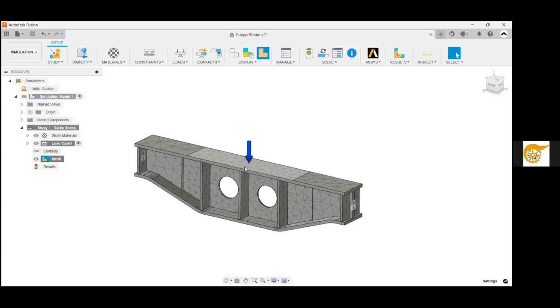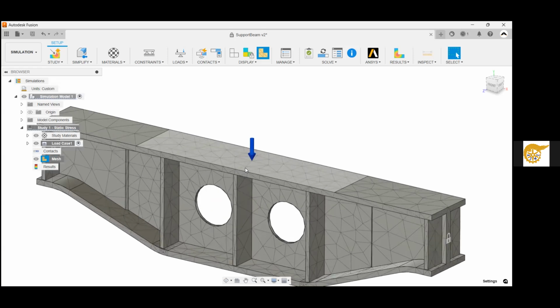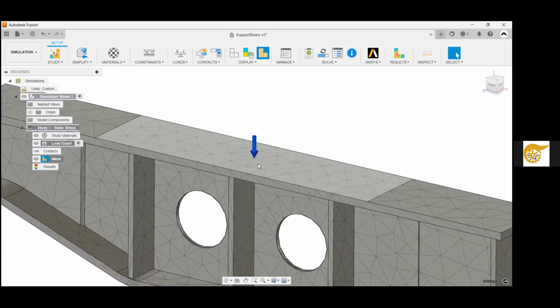You want a fine mesh in areas that are small, especially. So, for instance, on the top face here, if we have, say, about 4 rows of rectangles, for instance, this would count as a rectangle, 2 triangles put together. And then the next one, it looks like the top face would be suitable. So we want about 4 rows of rectangles, right?